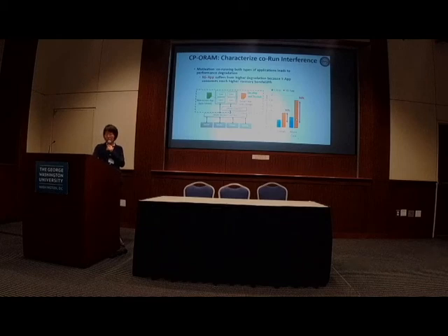So we looked at this problem and see that, okay, obviously, such a performance hit is generated by the mix of memory traffic from both secure and non-secure applications, and the non-secure application suffers because most of the memory traffic is generated from the Path ORAM of the secure applications. So you could come up with some solutions. For example, can you separate them onto different memory channels? A server usually has multiple memory channels, let's say 4. Can you put the secure application on a single channel and leave the rest of 3 for the non-secure application?